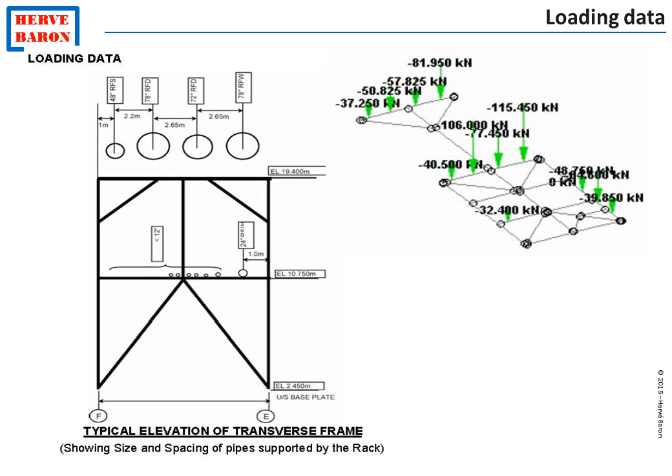Besides loads from the pipes themselves, the design of the pipe rack takes into account the loads due to the wind as well as to seismic action where it is applicable. Not all loads are applied simultaneously. The code specifies the relevant combination of loads.